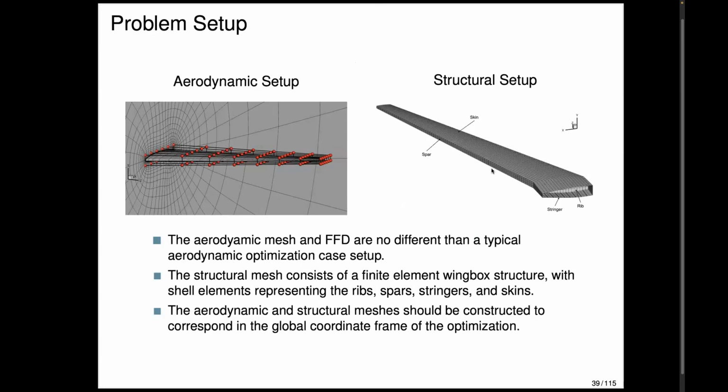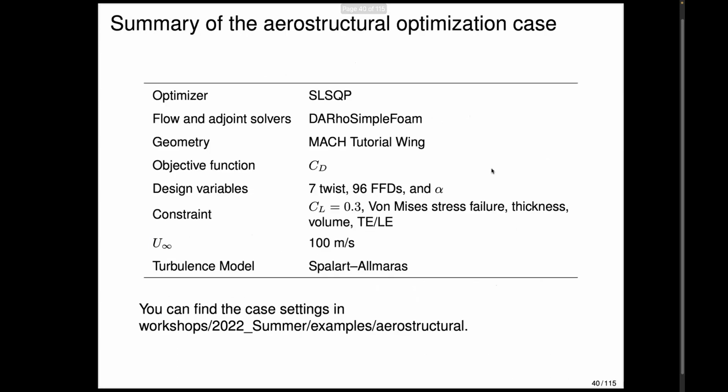So this is how you do the problem setup, and just remember to make sure that when you do the case configuration, everything aligns properly, so that your meshes do overlap as you intend them to, even though they are two separate simulations. So we'll go through what we call the mock tutorial optimization case. This is something that's publicly available online from the MDO lab. In this case, we'll show how to use it with DAFoam and MFIS.